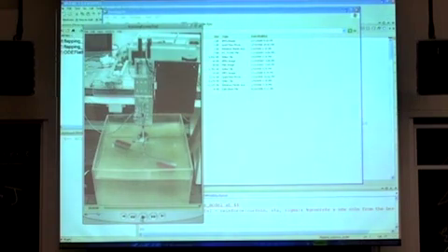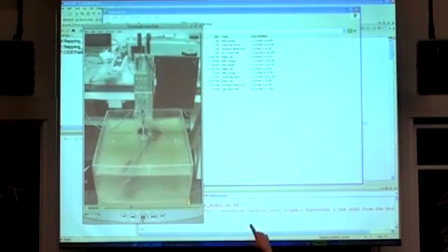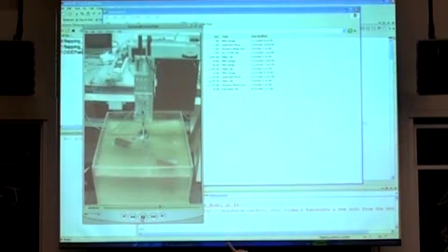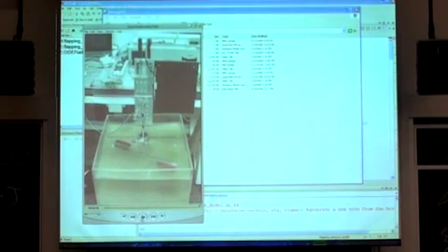All right, so this is the system. You can see we drive it up and down. That big cylindrical disc right there is a load cell, so that measures the force we're applying. And then what we do is we control this vertical motion. How we control it is another important thing.